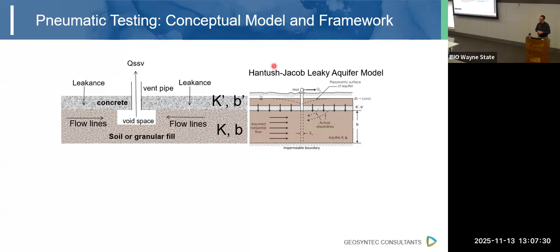And we have a hydrogeologic model that describes how water in that aquifer moves. We can just repurpose that for this scenario. It's still fluid flow through porous media. It's just air instead of water and concrete instead of clay.